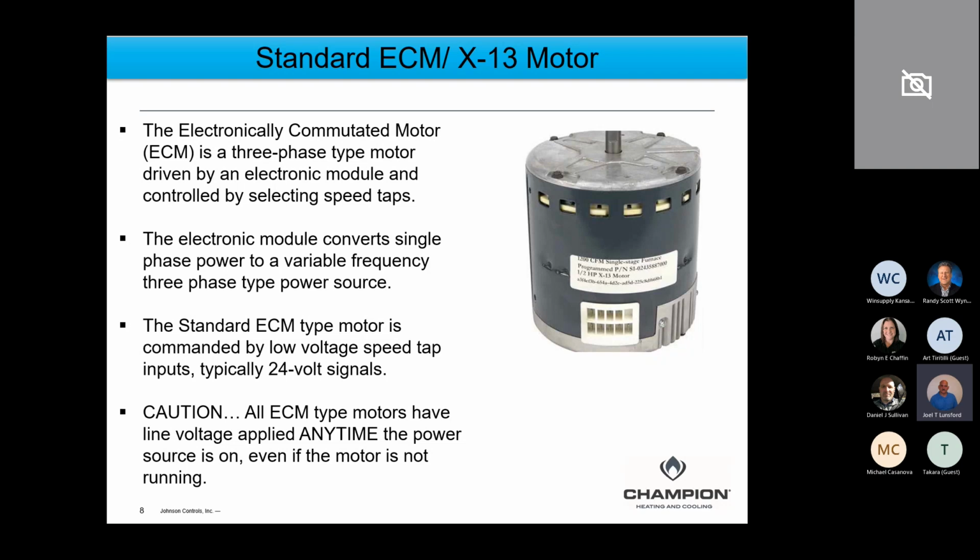And so you want to make sure that if you remove an ECM motor, or you unplug it or shut the power off, don't take it apart. Don't touch those line voltage terminals for at least 5 or 10 minutes. Let that motor sit there and discharge those capacitors for safety.